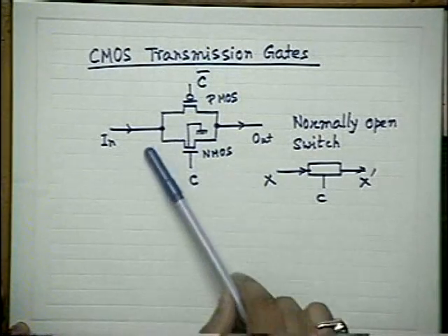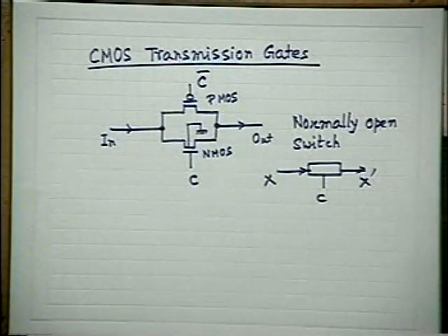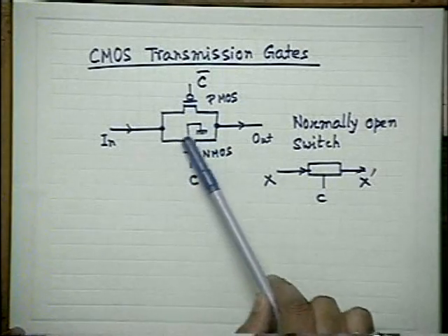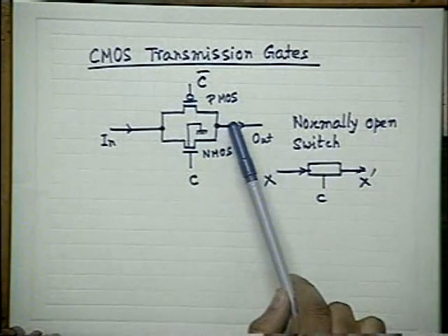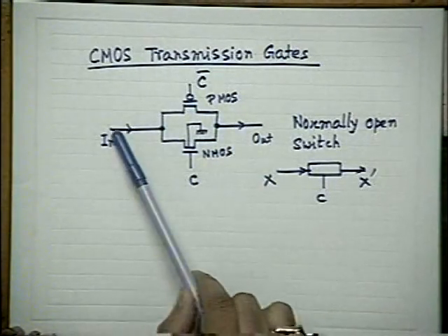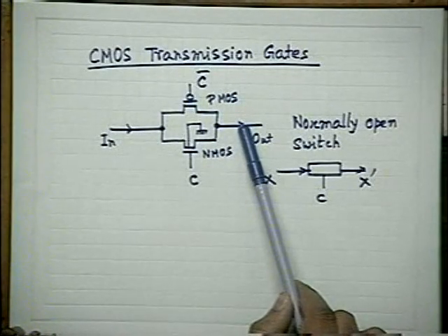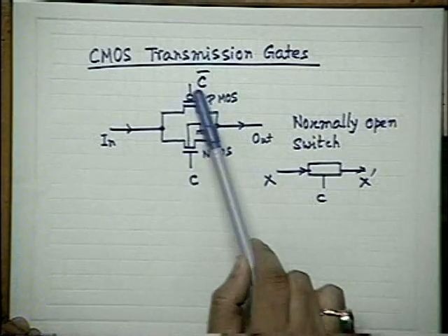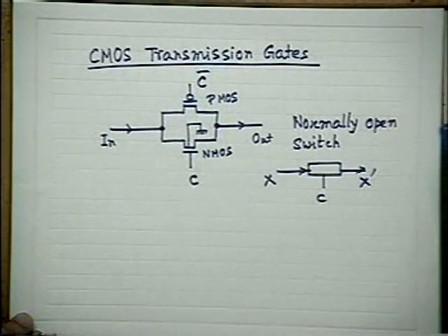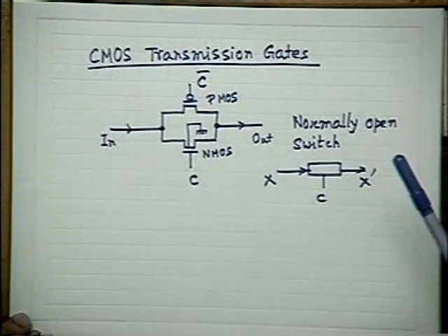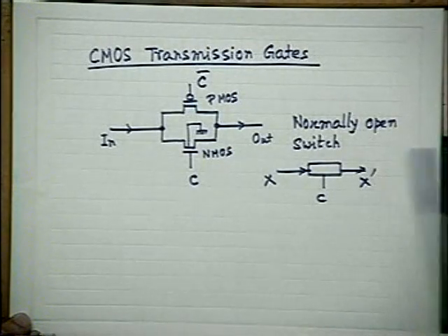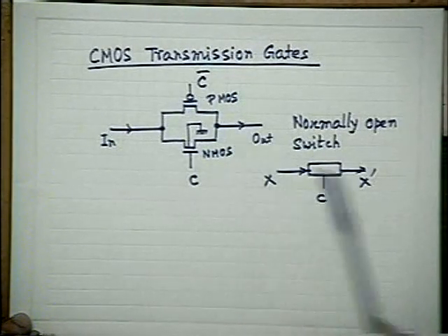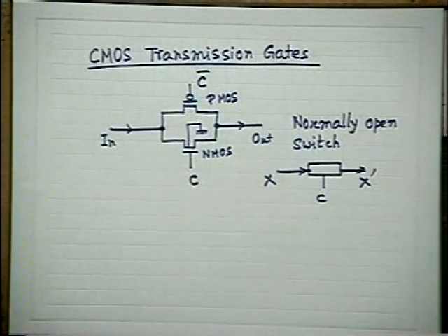This transistor will be again in saturation. It will be on, but it will be in saturation. And we expect a voltage. What is the voltage now? Again VDD minus VT. But this will be counteracted by this PMOS, which will be very heavily on and in linear region, and will help in the passing of the entire voltage. You can check it yourself.